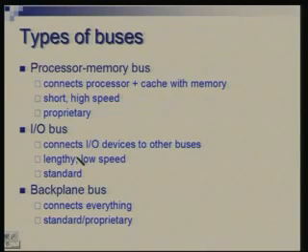The design of these is proprietary. They are not standard. Standardization is required when you need to connect a large variety of subsystems, as you would see in the other two scenarios. So these are defined for a specific case. So let us say you have a system based on Intel's Pentium 4. So depending upon the signals which are there in Pentium, you need to connect that to memory, and a bus would be designed specifically keeping in mind the Pentium's behavior.